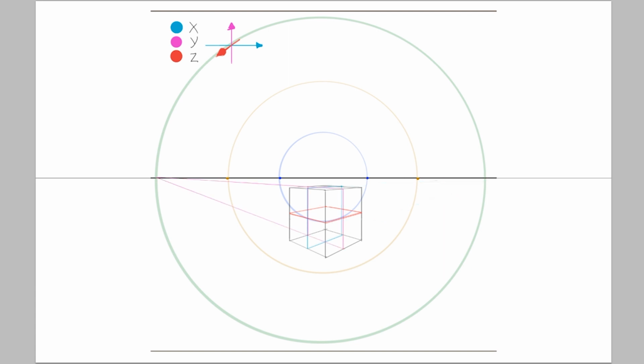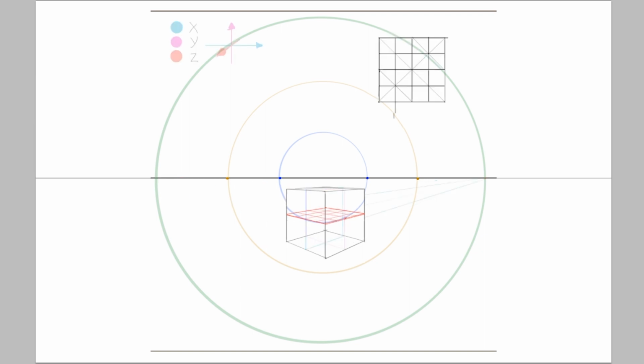Once we have these halfway points marked, the next stage is going to be to pick one of these halfway planes to plot an ellipse in, which will go about in exactly the same way we have for the cylinder, plotting out our points and then dropping in an ellipse. Once we've done this for one axis, it's simply a matter of repeating the same steps for the other 2 axes.